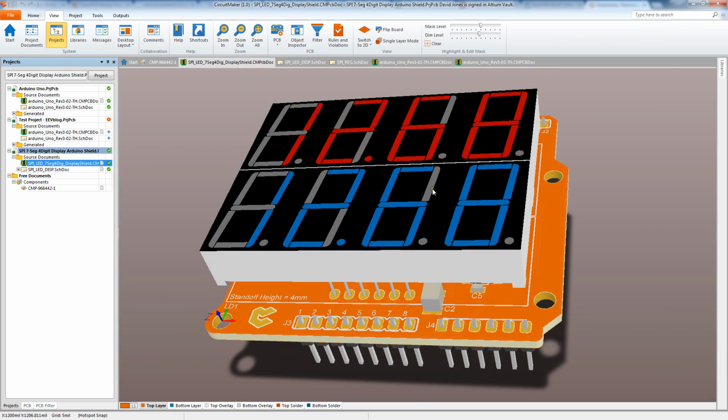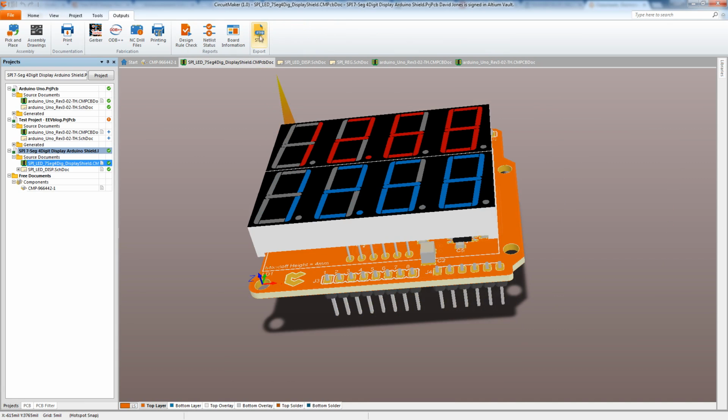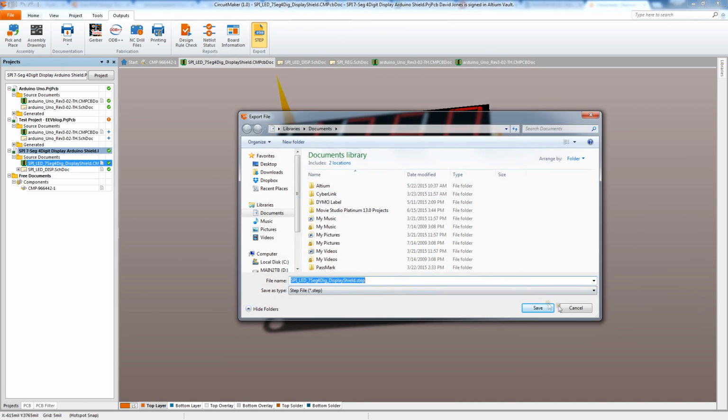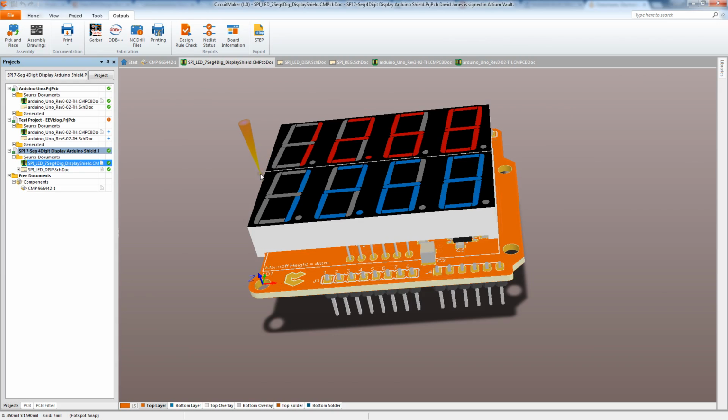It's one of the most powerful features of Altium Designer, not just to see the 3D components like this, but just to see the bare board, even if you don't have the 3D component information on there, being able to see your solder mask and everything else, fantastic. And it's nice that you can actually take your board and export that as a STEP file too, to put in some other 3D package. Terrific. And yeah, everything's just like Altium Designer. I feel completely at home.